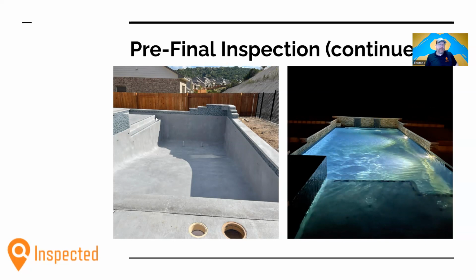If there is a step or a set of benches, in this case, or a bench and a beach, you don't need a handhold. But again, back in front of this raised multiple spillover spa, if this is in water deeper than 3'6", you have to have a handhold somewhere here. It needs to be above the water line, not below.